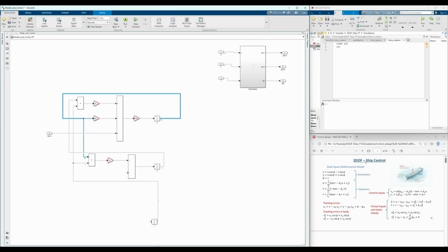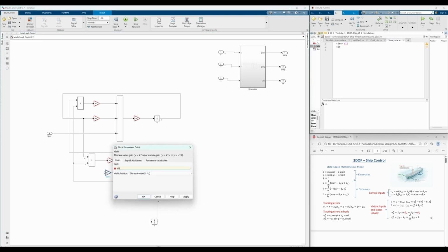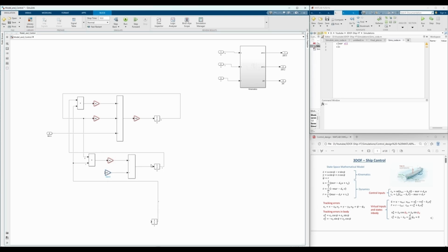You see, now this double click works because we have 2 connections from this one line. And the next one is dV times V. So dV, I will have to change this from du to dV, and then times V. So this is V, and I will connect it over here. So if you double click, it's V. Now, one thing I missed over here is that we have 1 by m as well before integrator. So I can directly copy it from over here.